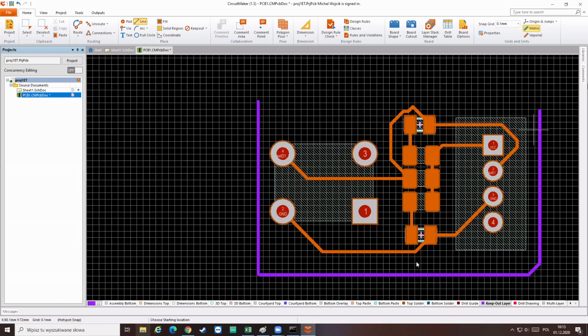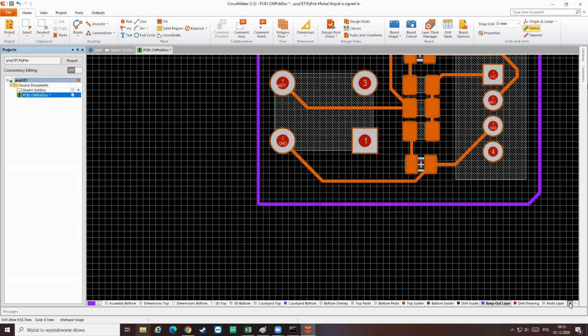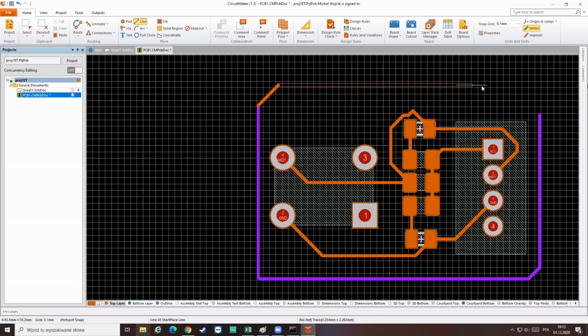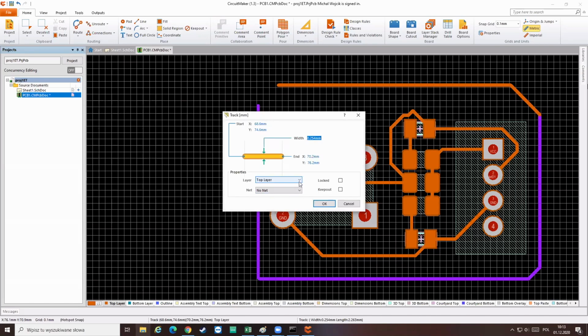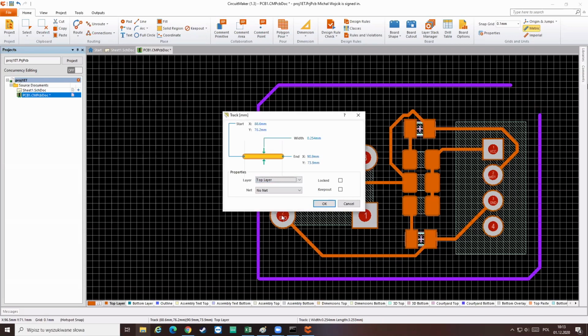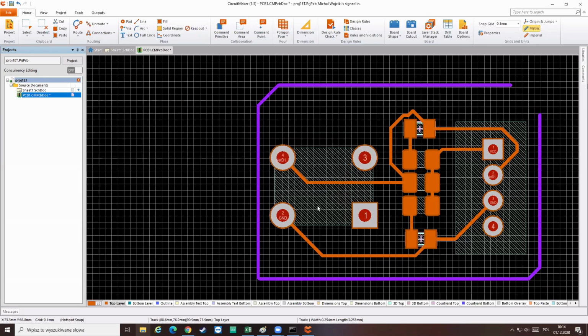Okay, if you at some point start making lines or elements on a different layer, let's say I would forget to change the layer to keep out and have made some border lines, you do not have to delete this. If you go to this option, double click it, you can always change the layer that it's laying on. So changing the layer of everything is possible if you just double click like I did just with this line in here. Okay, so now I get the keep out layer, so I now have the border of my board.